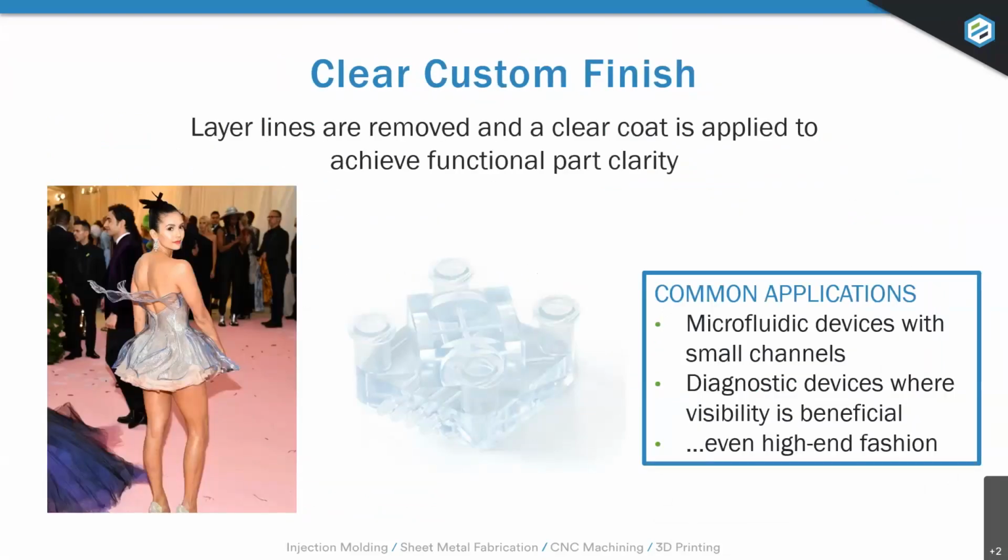There are a number of custom finishes we can offer. Clear finishing is one of the most common. This entails sanding the external layer lines to a very fine grit and applying a polyurethane clear coat. Common applications are microfluidics, diagnostic devices, and light pipes.